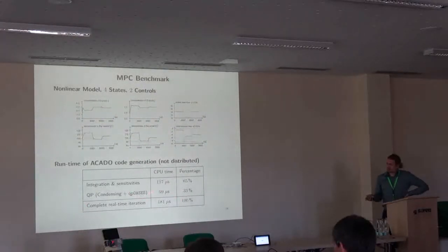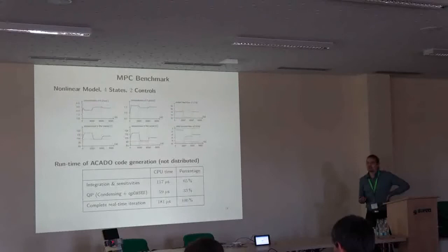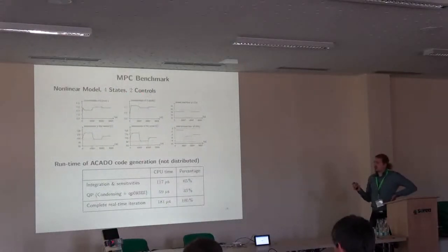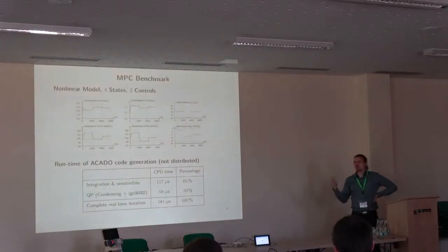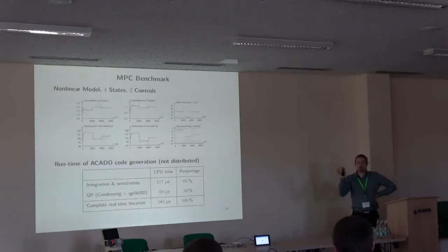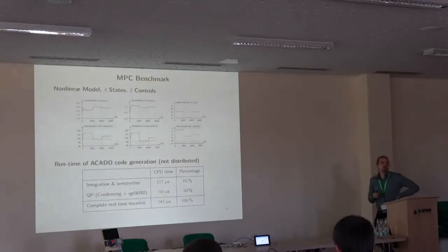Yeah, so in this case, we used qpOASES, which is an active set QP solver, or an online variant of that, in order to reach these computation times, which is pretty feasible for systems with 4 states, 2 controls. We have them running, for example, on model predictive control of kites, which have more like 22, 24 states and something like 4 or 5 control inputs. In that case, you would probably get runtimes in the range of 1 to 10 milliseconds. So if you scale it up to 20 states, 5 variables, if you want to run that on bigger case studies, that's completely feasible.